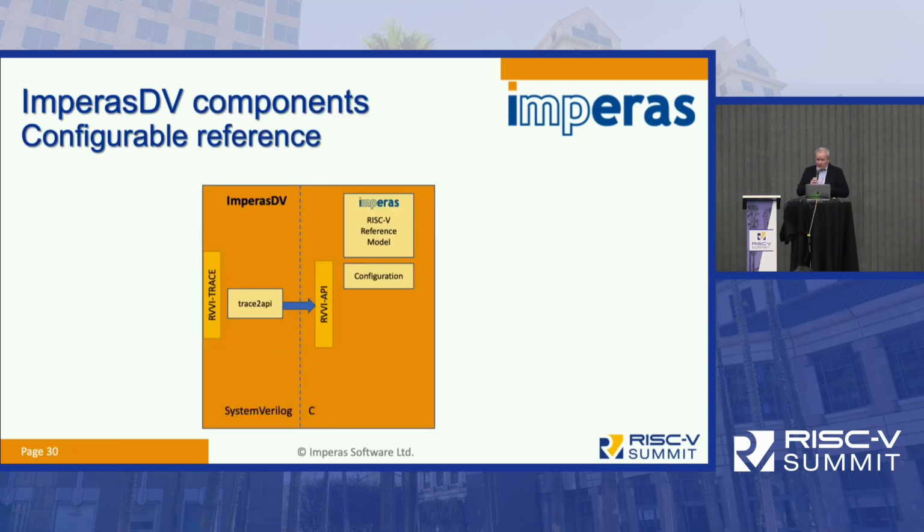So let's just go through what the components of the RISC-V IP actually are. You'll see here from this diagram that we have, first of all, the ability to configure the reference model. Then you have to be able to do the synchronization. This is an important block so that when you do the execution, typically what's happening is you execute an instruction to retirement on the target, and then you do the same on the reference, and then you do your comparisons.